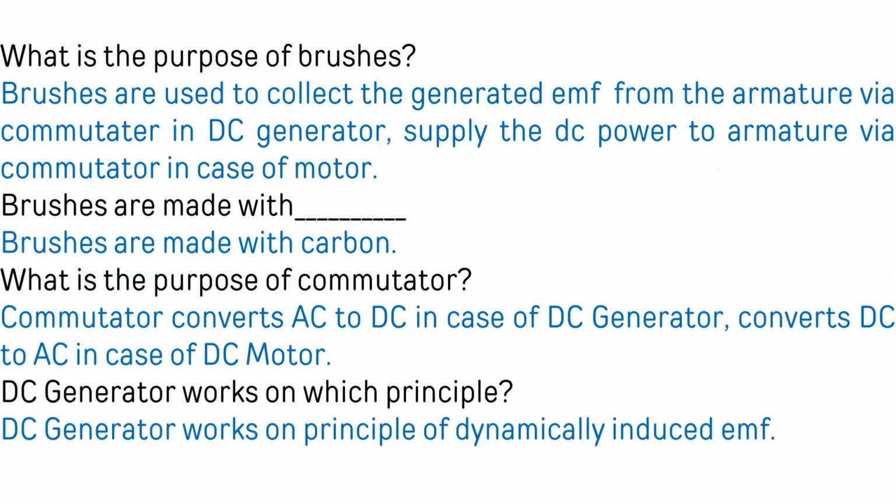What is the purpose of brushes? Brushes are used to collect the generated EMF from the armature via commutator in DC generator, and to supply the DC power to the armature via commutator in case of motor. Brushes are made with carbon.